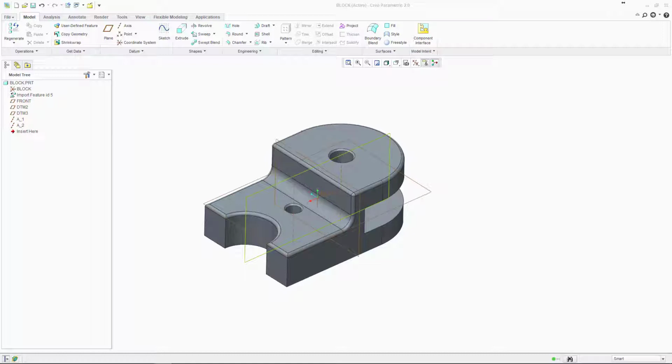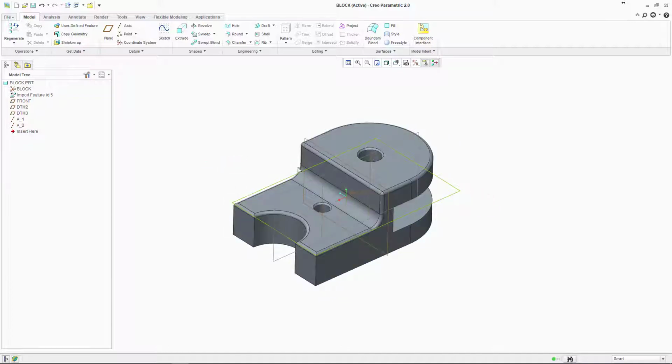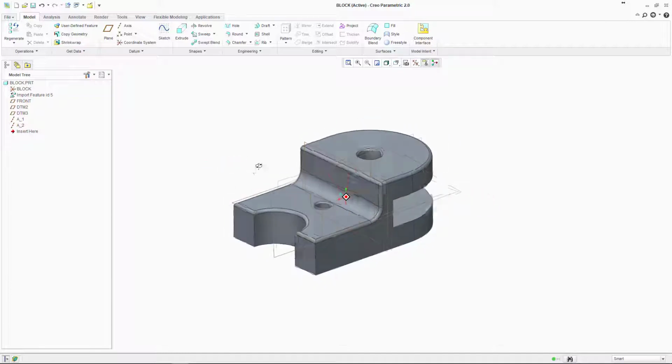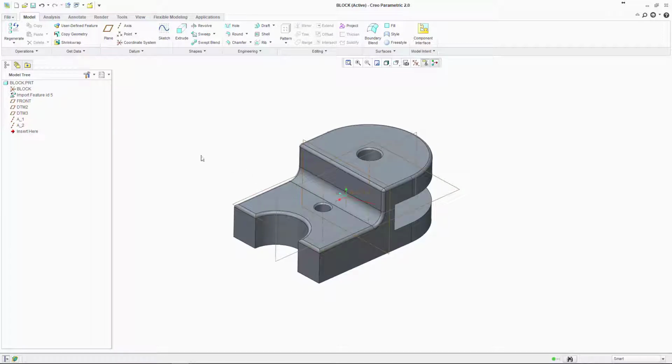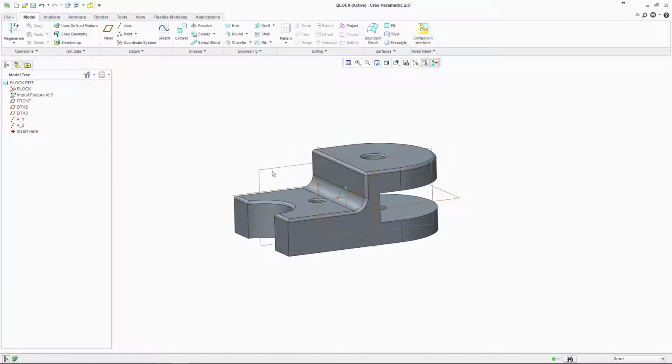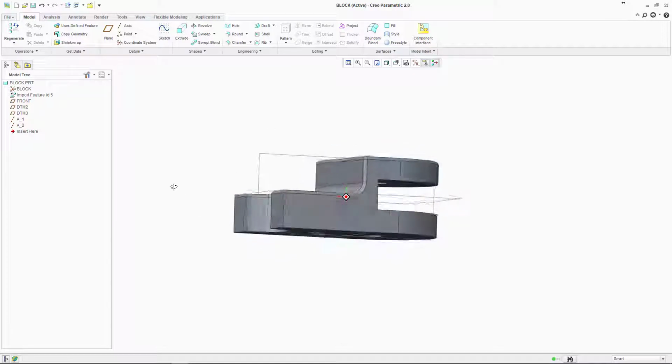So at that point, that's the end of the tutorial, and essentially what we've created there is we brought some surface data from the IGES file that had holes and errors in the geometry. We've fixed all the geometry. We've converted that surface geometry into a solid part, and then we've added in our datum features that allow us to then use that part further on down the line.